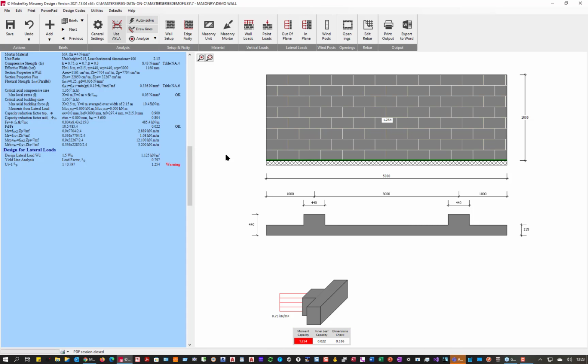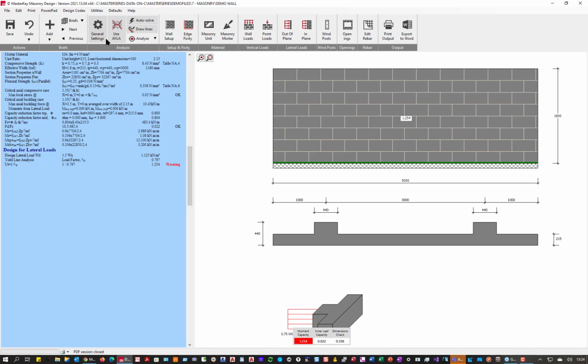It's actually the one I hate because there's so many walls standing that don't work to the codes of practice, because our load factors and our gammas on our materials are so stringent. If we look at this wall, it's 1.8 high. We're failing by 25%. So our piers are 3 meter centers. I could pull those closer by 25-30% and get it to work.